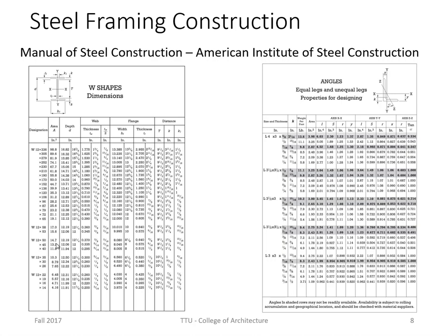What's useful for you, though, is to know what the standard depths are. So when you're designing, you don't want to choose a depth that is visually out of the range of the standard, unless you really have to. So that's the reason to be aware of the different standard depths of the beam and the widths of the flange from an aesthetic point of view.